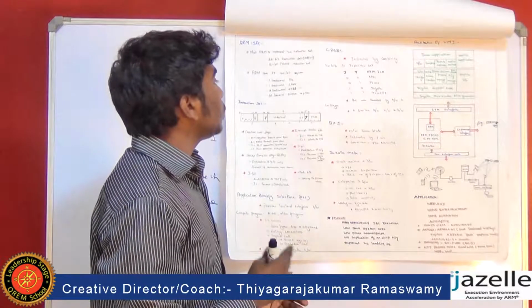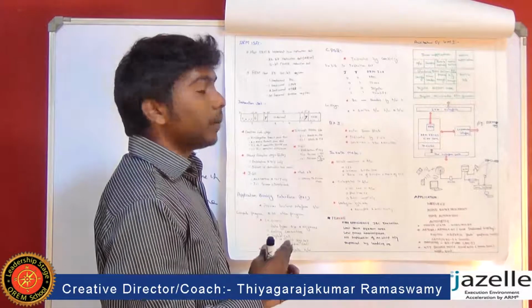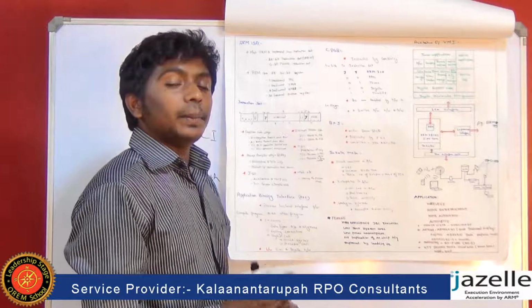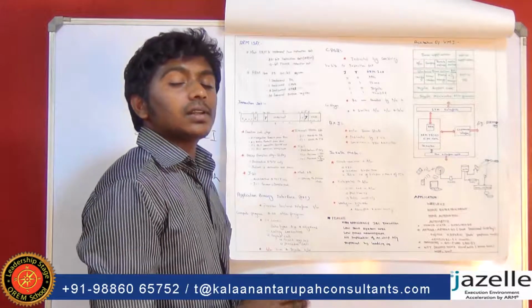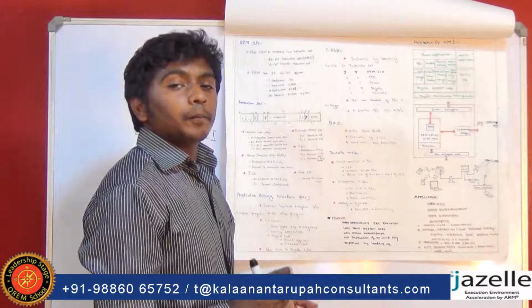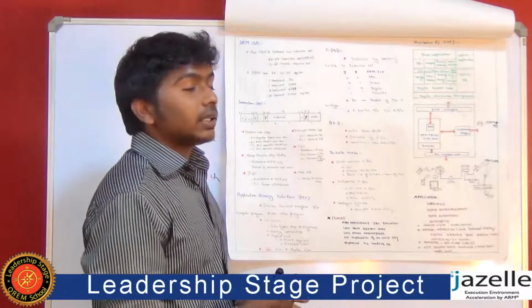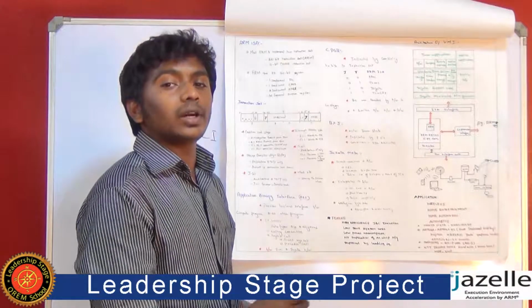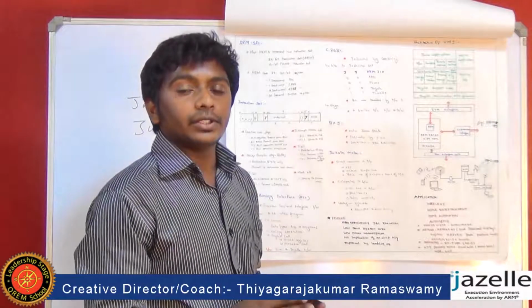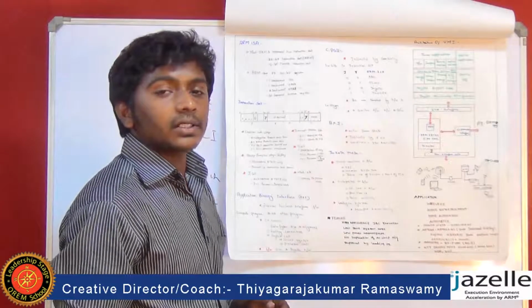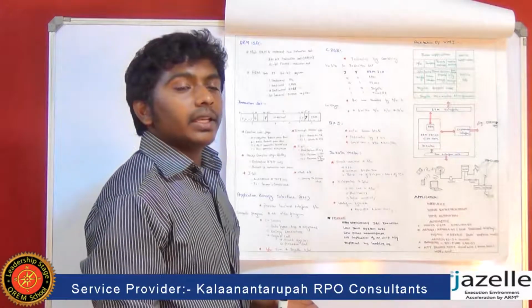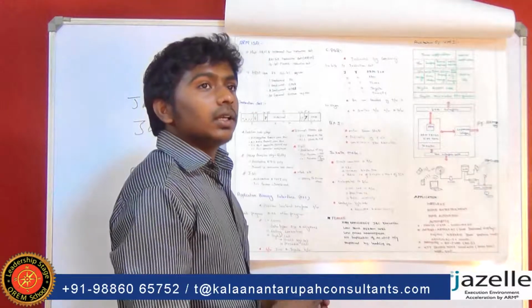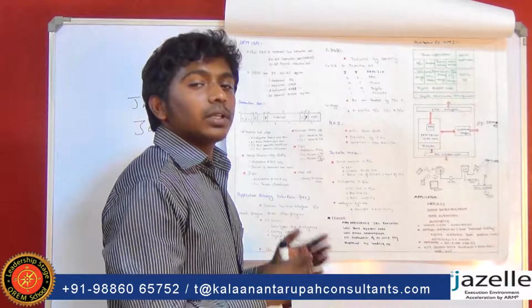And ARM has 37 32-bit registers. It includes one PC register and one CPSR, that is current program status register. It is used to store the current status of the execution, so that if any error occurs or any reboot takes place, the state can be resumed and started.